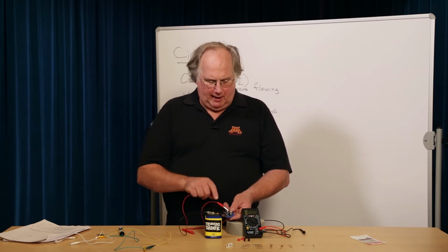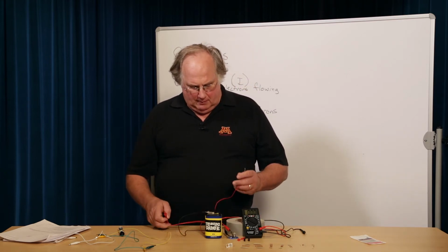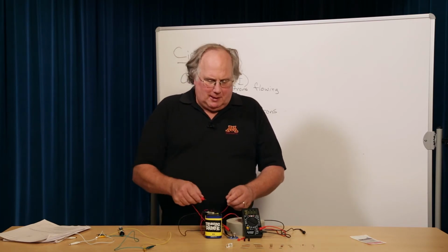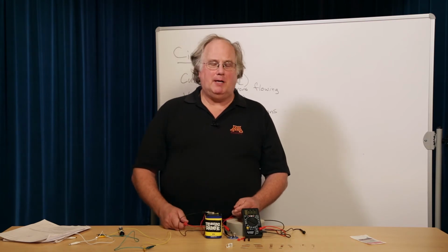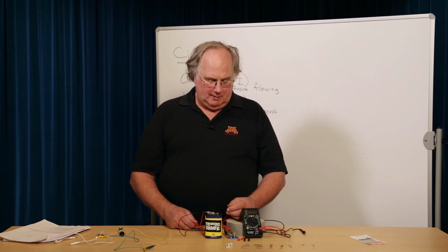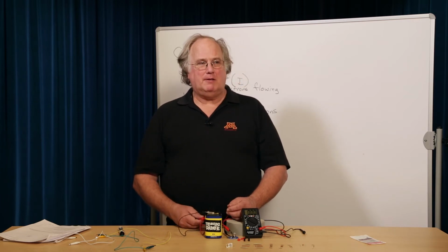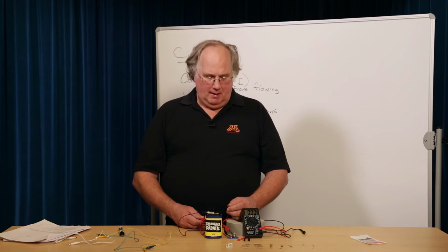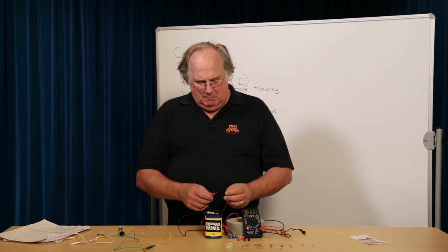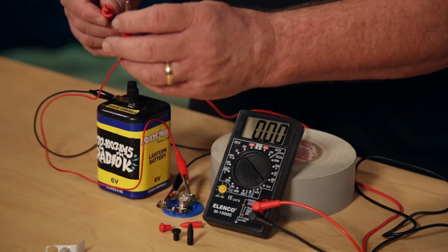To measure the amount of amperage, the current going through this bulb, I have to do things a little more complicated here, because measuring voltage you can do by just putting the probes on 2 points and it will measure the voltage between them. Measuring the current, on the other hand, means you have to route the electrons through the meter, so you can count how many of them go by. And that means to measure current, you have to put the meter into the circuit like this.